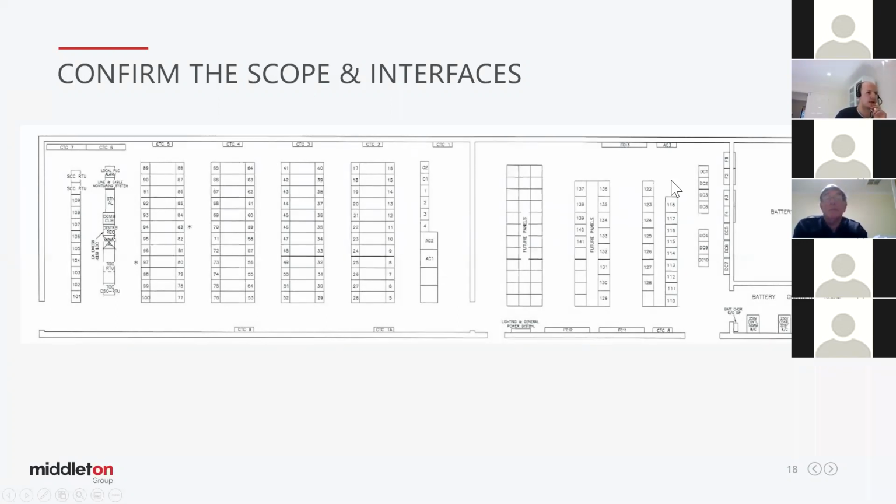When you look on the right over here, the way these panels are represented are generally freestanding. So they're full cubicle height and width, and they would be, as they are called, freestanding. They would be just bolted to the ground, with earth straps between each panel in two locations, just for the continuity of that earthing arrangement. And then you might find that you have cable trays over top with this particular arrangement, while with the frame type arrangement, you might find that the cable access is underneath rather than on top. So it's a different arrangement. Again, it depends on the vintage of the site. You may have cable trays on top, but that depends on site requirements.